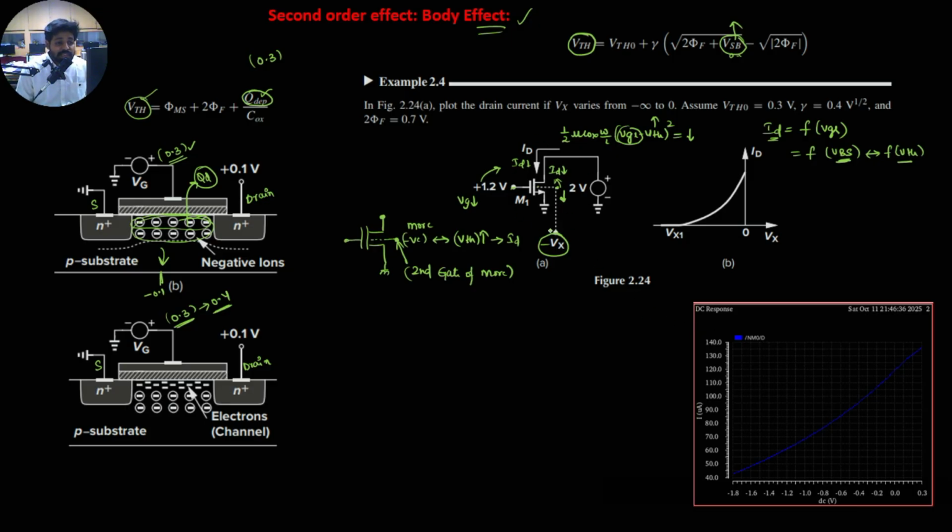So we make the setup here like this, and we will be changing the body voltage. We are making the body voltage more negative, and we will see the drain current falling. As we are observing here, as VBS is reduced, VTH is raised, so the total current has to fall. That's the practical way of simulating the body effect. That's what we do in the tool.